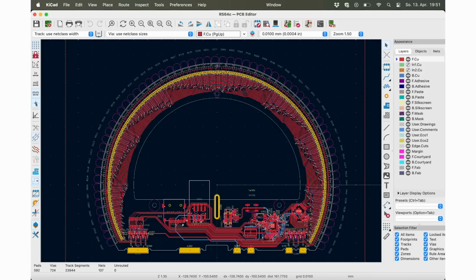This is the layout of the LED board. Implementing the LED matrix results in a large number of control lines which are routed in circular patterns around the LEDs. The LED board is a 4-layer PCB. The 2 inner layers are used as continuous grounding planes. This design choice was made because the LEDs are driven by short, high-current pulses with steep signal edges.